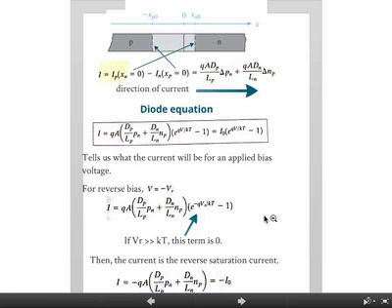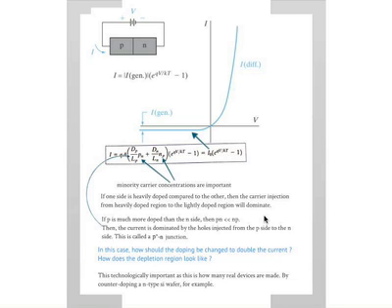And you can see it depends on the diffusion coefficients, basically. So if you look at the plot which I showed before, this is the voltage, that's the current. You can have a generation current here, which is the first term, and then an exponential term, which is defined by that part. The minority carrier concentrations are the most important thing that determine the current, because remember, it's a minority carrier diffusion that causes this.